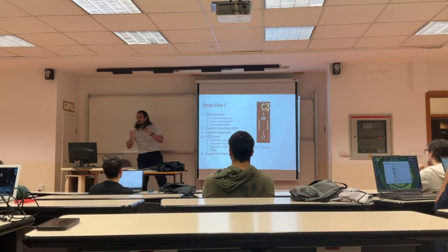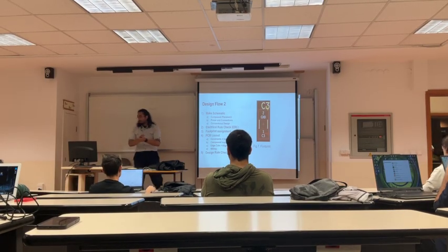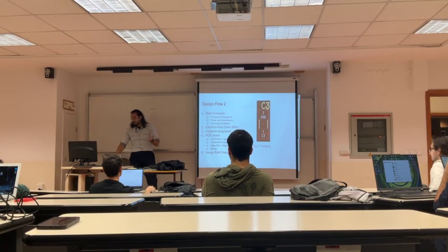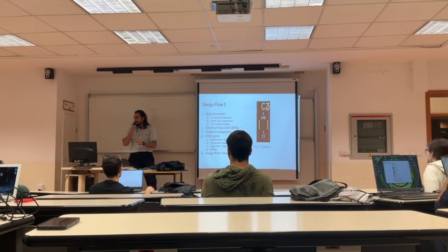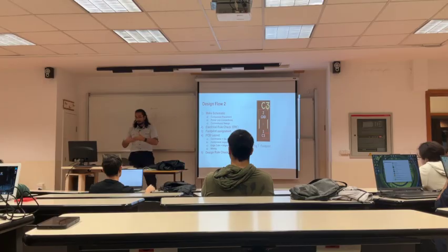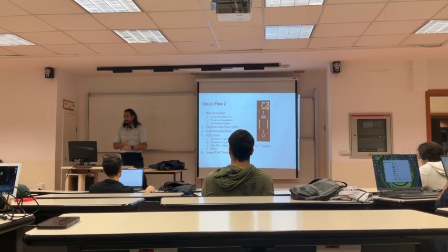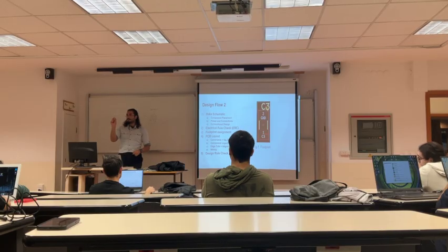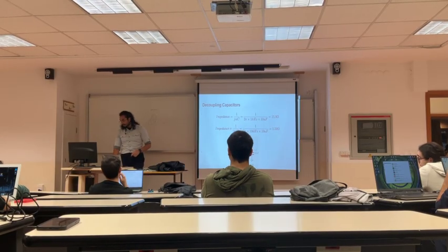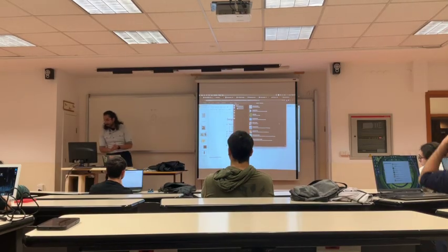And we do the PCB layout, we arrange the components, we wire them through, and then we do a design rule check, which is like an electrical rule check. We check the PCB layout if everything is correct, if everything's connected, if the distances are manufacturable, etc. Okay. We will do these later. You can go ahead with KiCAD.